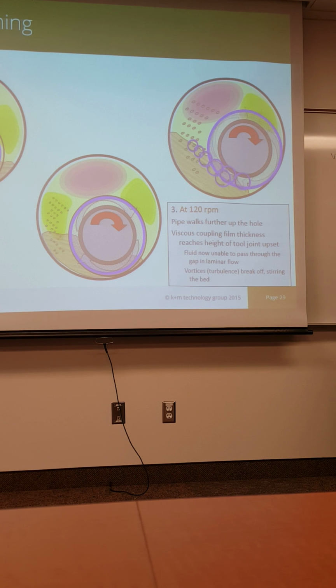The reason why we think that's the case is because most drill pipe has a consistent gap between the tube and the tool joint. Most of them are about 5/8 to 3/4 of an inch gap between the tool joint and the tube.